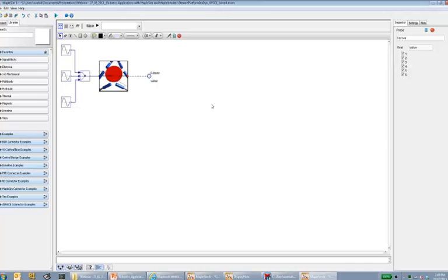So what we would see, and there's a slide that I will show you after I've gone back to the presentation, is that we will get a huge boost in the time for the calculation required for the inverse dynamic. The first option was the traditional, or straightforward, way of having two Stewart platforms, one for inverse dynamic and one for inverse kinematic. The second option was to solve the inverse kinematic and implement that. And the third, that we see on the screen, is just to calculate everything into one big function and implement that.